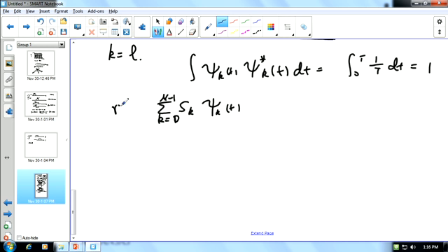And that's our received signal. That's the basic idea of OFDMA, orthogonal frequency division multiple access. Any question? So the spacing between the frequencies depends on the duration of the pulse. Yes, exactly.